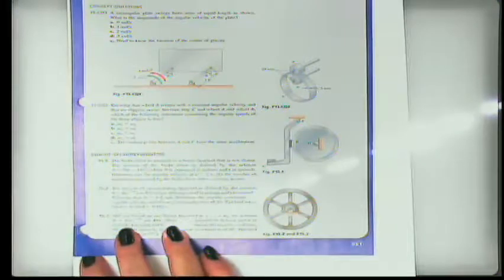Now, one of the things that's really interesting about flywheels from an application point of view is a lot of things that need to store energy, especially angular energy, will use a flywheel. They have extremely high masses, and so they're slow to spin up, but they're slow to spin down. So especially in big, heavy machinery, you see a lot of flywheels, but there are also flywheels in your car and all kinds of other places. So they're kind of interesting. And they're a classical engineering solution to a lot of different kinds of problems.